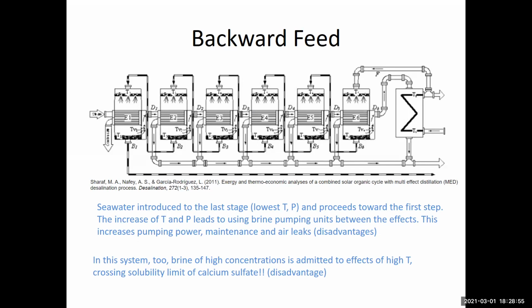What is the saturation point? It is the temperature at which the salt crystals can be separated and stay on the surface, scaling. Scaling increases as the temperature increases. So this is basically the bad thing about this layout. That's why you can seldom find a backward feed operation system. Maybe it can be done for brackish water, for example, but not for salty water with high salinity of salt.